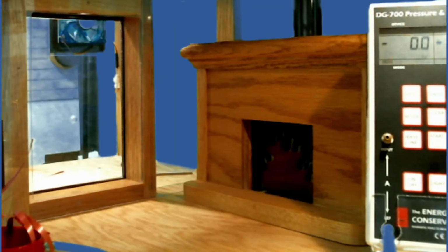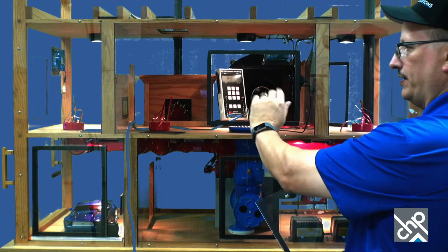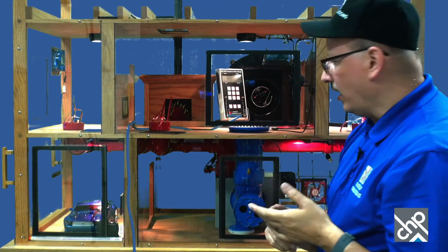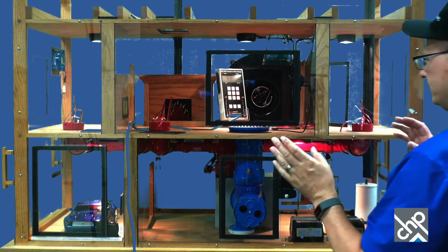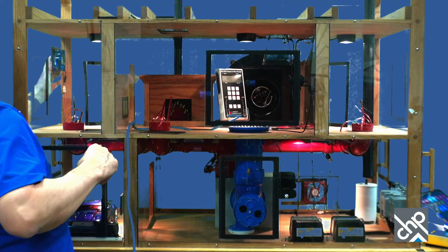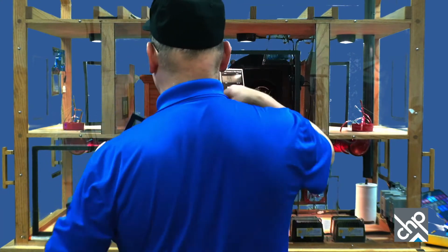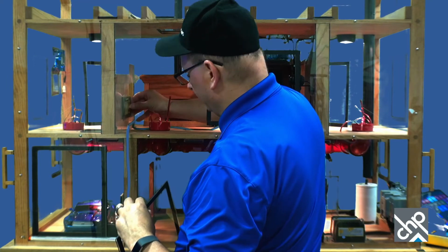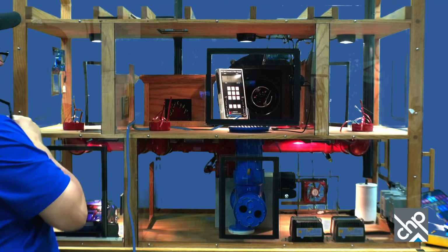All right, so I'm going to go back out here. So there's the manometer inside. You can see the number, the zero there, the number on the left. That's the one we want to focus on. I'm going to put this back on. So we have all of our appliances off. All exhaust fans are off. Interior doors all need to be open. And so I think we're ready to go. I'm going to put this little door back on the vent on the interior wall here, where my pressure relief was.